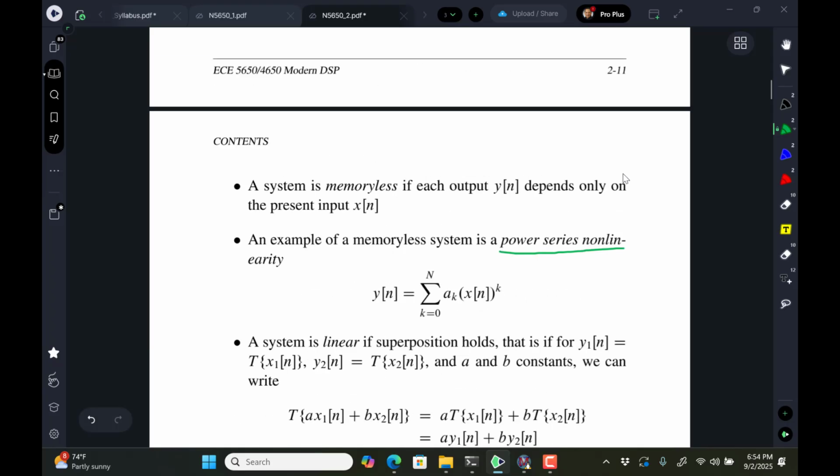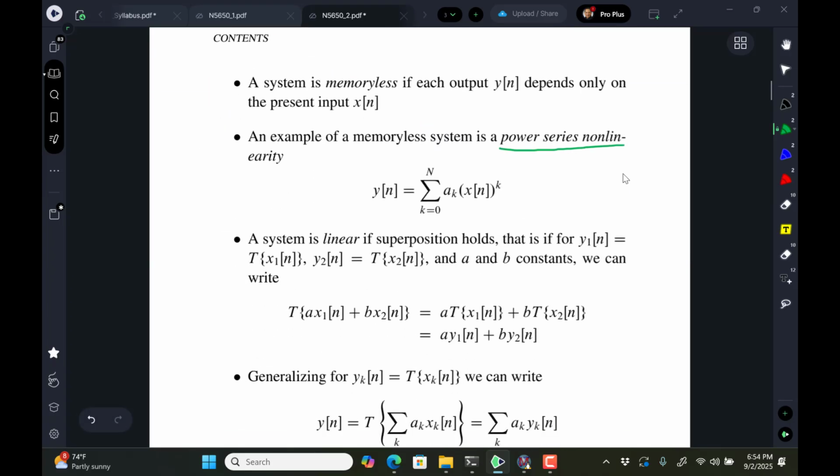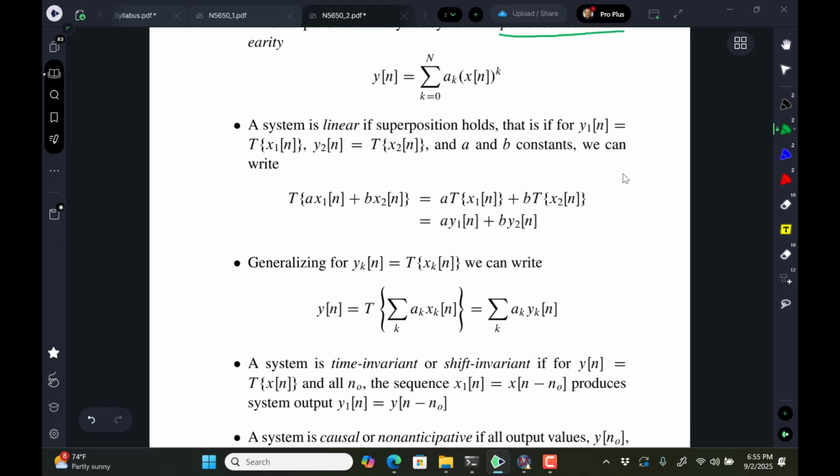We got off of this example because in my notes, that gray bar just means that example was ended. So now we're just back into the regular routine, and we're going through the definition. So linearity means superposition holds, which means a linear combination of inputs can be sent through the system to give an output, or we could send the individual inputs through the system one at a time and then gain scale them accordingly to form the output.